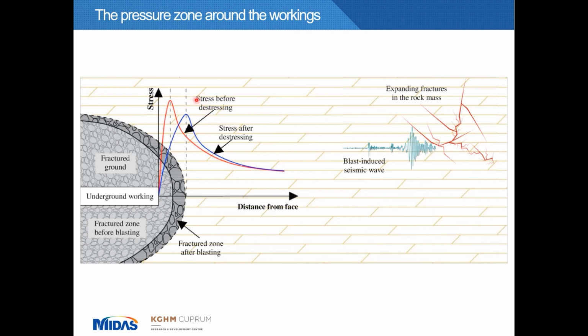And for this purpose, the so-called active rockburst prevention is used. This active rockburst prevention includes, for example, the multi-phase distress blasting or torpedo blasting in the roof. And the base assumption is that if blasting is effective, then rocks in the zone of increased stresses crack, and the danger zone moves deeper into the rock mass. Of course, it affects the geotechnical threat, which decreases as a result of these actions.